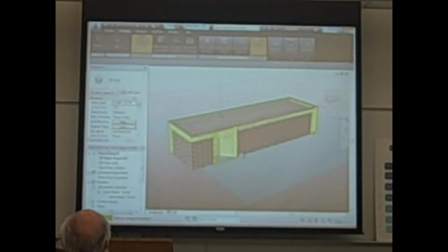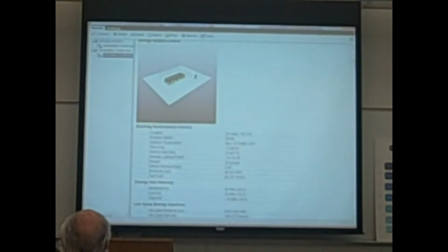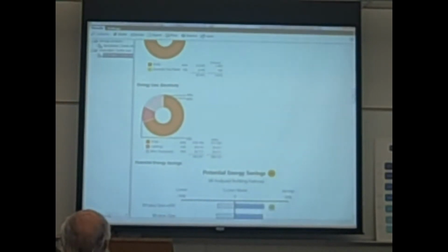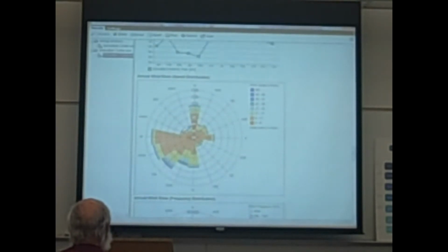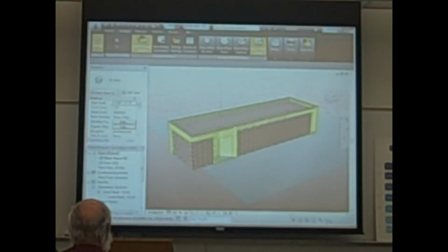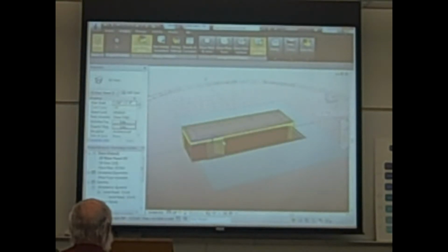This leverages some of the cloud technology as well. It takes this model, it's understanding the glazing. You can adjust building materials. You tell it what type of construction it is. You tell it what percentage of the envelope is going to be glazing. You can tell it what kind of shading you're going to use. And then as it uploads into the cloud, this is what comes back about your project in terms of overall energy use for an entire year. And so now at this point, maybe we rotate the building, or we change the percentage of glazing, or the way we're going to cool it. All of these are factors that can contribute to making this thing a better project.